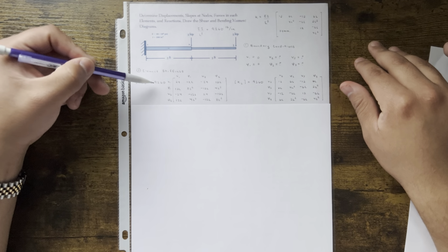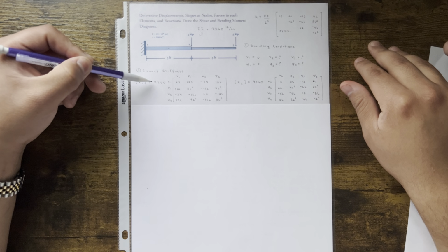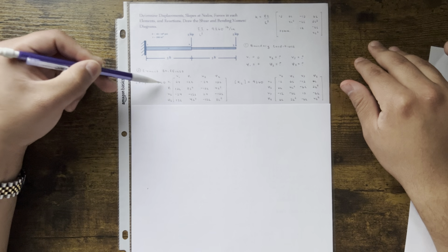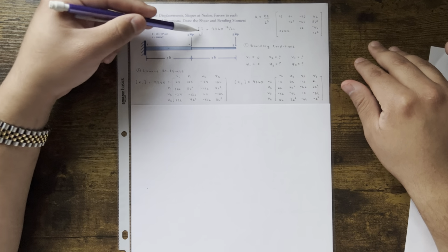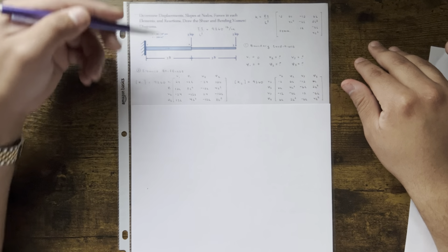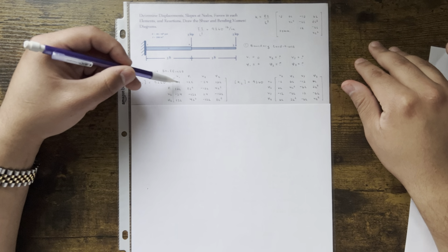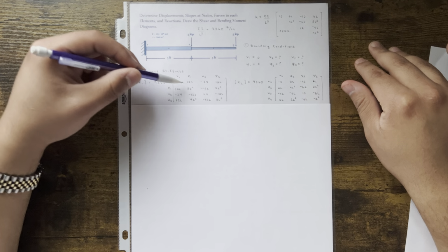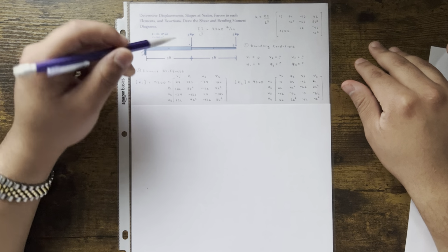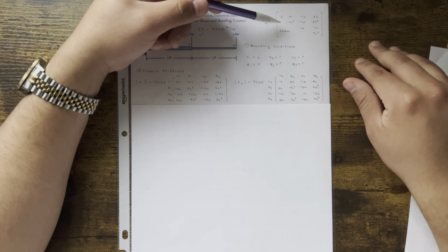So for element 1, you were supposed to get 18520 on this side, but I only put 9260. Instead, since this was 2 times EI over L cubed, instead of multiplying this by 2, I multiplied everything inside by 2. So look, this was 12, 4L squared, 12, 4L squared that got converted to 24, 8L squared, 24, 8L squared. And everything in that matrix also got converted, okay?